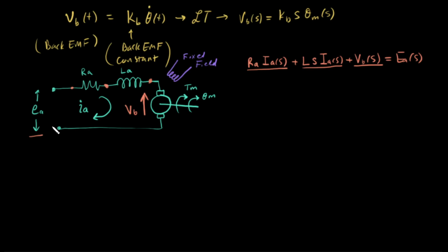So this gives us our motor equation, and we know through other ways of modeling or experience, we can say that the torque in the motor, and notice we're just going ahead and doing this in the Laplace domain, is KT times IA of S. And what we're saying here is that the torque output from a DC motor is proportional to the current. And this term here, KT, is what we call our torque constant. Okay, so KT is our torque constant for that motor.